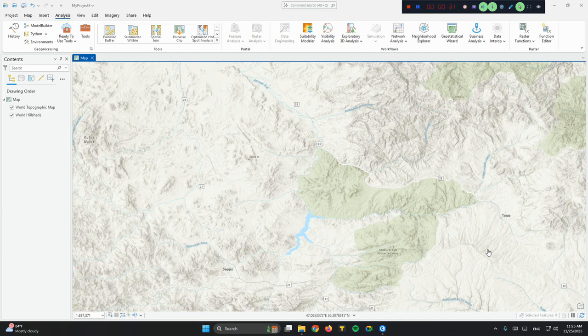Before we get to the methodology of how we can extract a watershed, first we need to understand the concept of it. A watershed, or catchment area, is an area that is topographically bounded, and it drains and collects all the precipitation through a common outlet, which we know as the pour point. It can be a river, bay, body of water, delta, or various other geographical conditions. The limits of a watershed are marked by natural features such as ridges, hills, mountains and cliffs. So that you understand, each watershed is divided by an elevation feature.